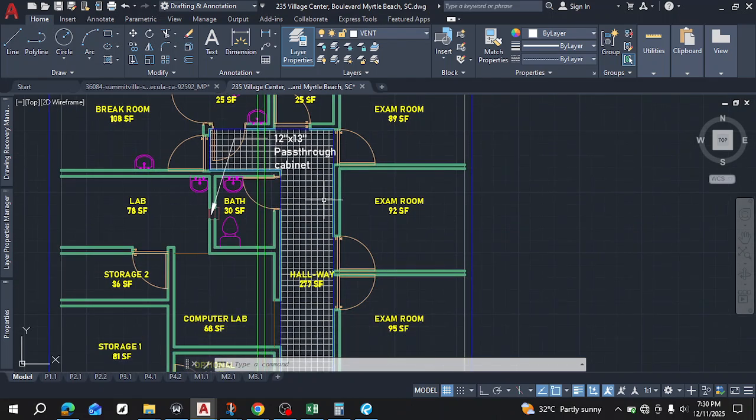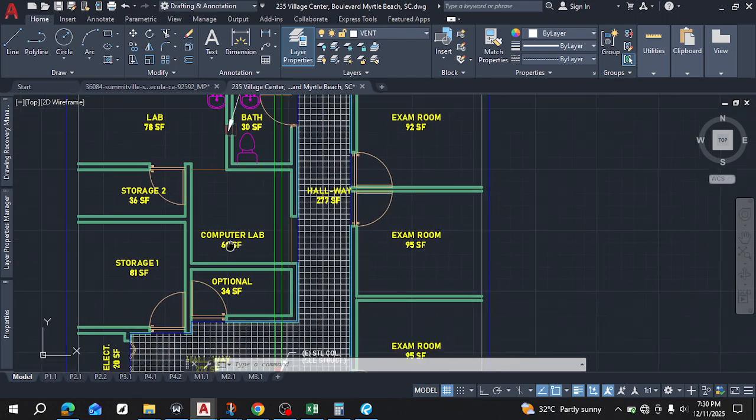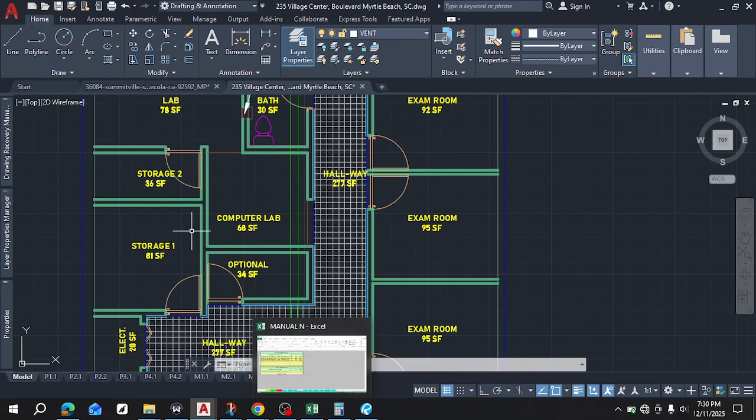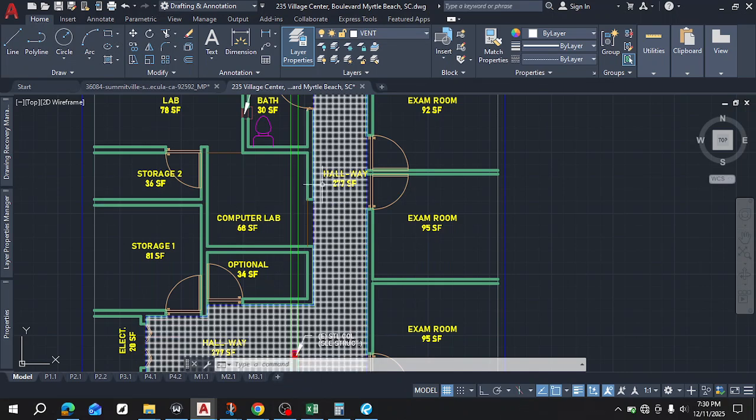This has a lot of walls, unfortunately, right? But basically, this is just going to be treated like one large wall, or one long wall that is just within this space. So the manual entry doesn't really permit you to start filling it. Imagine having to fill in information on this one after the other. So you get the entire length and then multiply by the height of that building, or the height of the walls.